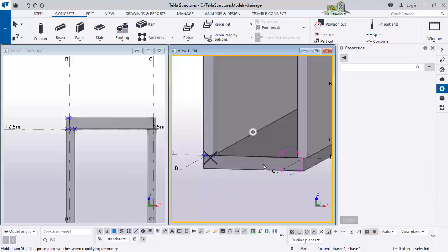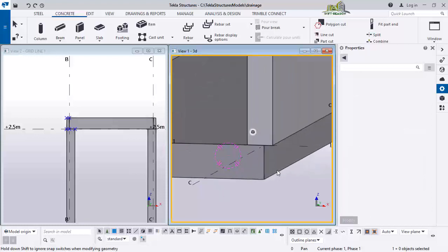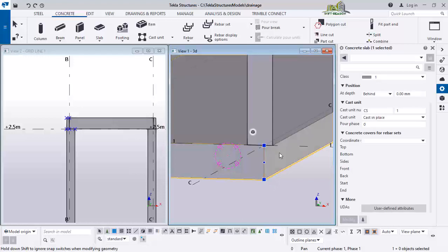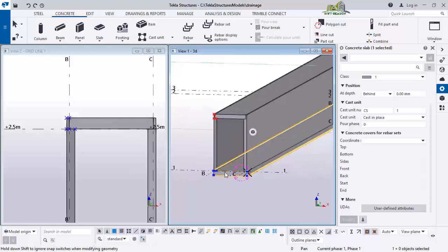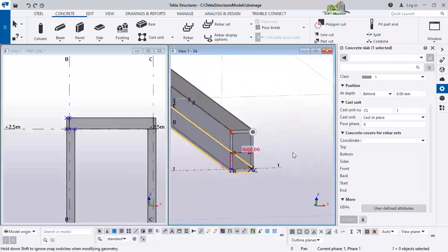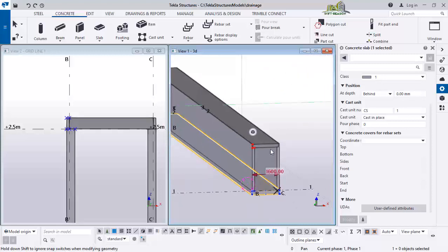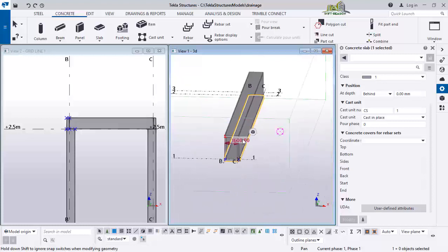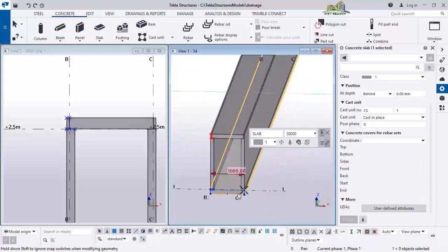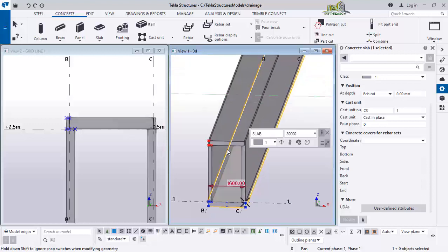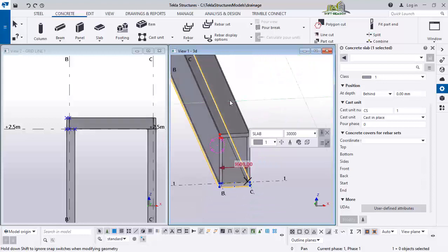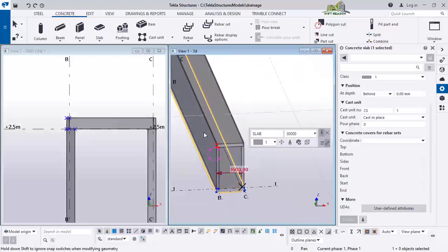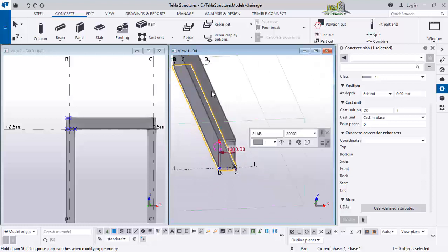Okay, so you also do the same thing here, select this, hold down the shift key, hold, and then drag it out. Right, just like this. So we have successfully created the wall of the drain as well as the top of the drain, and then the floor. Okay, so the next thing we will be looking at is how to create a opening for inspection.